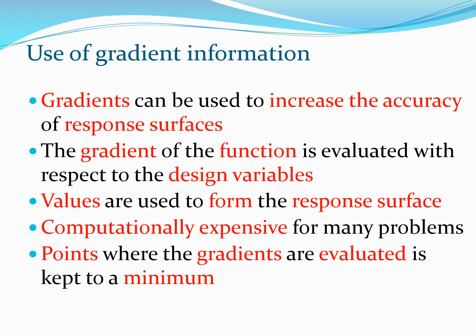Now one more possibility is to use gradients to enhance the response surfaces. And this essentially requires you to calculate the gradient of the function at a certain point with respect to the design variable, and the value of the gradients are also used when forming the response surface. So essentially the response surface would capture or fit your curve to the gradient value at some point.